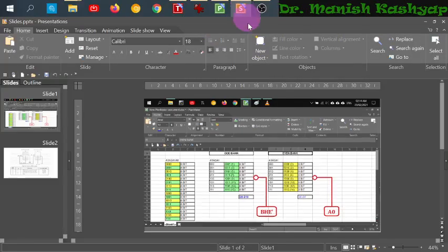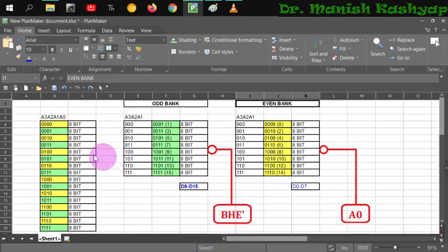Again, let us come back to what we have discussed in the previous lecture. In the pilot example that we have discussed, if you have a single chip versus 2 chips, then with 2 chips, one less address line is required. You do not require 4 address lines here, although for the original chip you require 4 address lines. However, if you break it into 2 parts, only 3 address lines will be required, and one bit, that is A0, will be used as the chip select for this particular signal. Right. So that's what we are going to do here also.